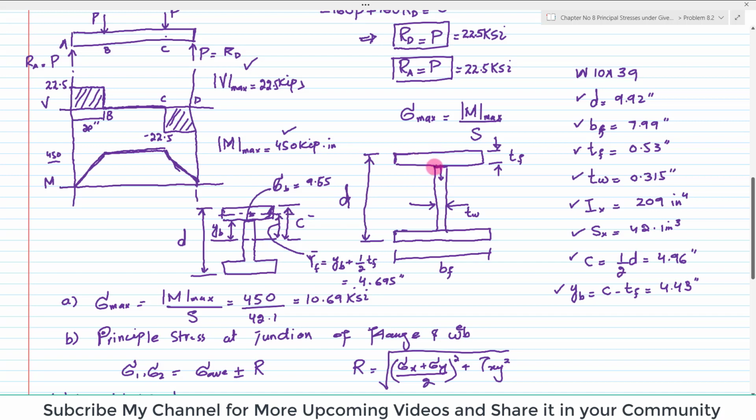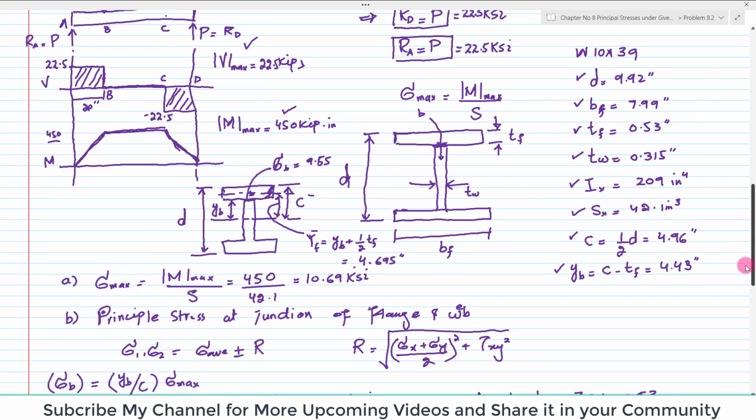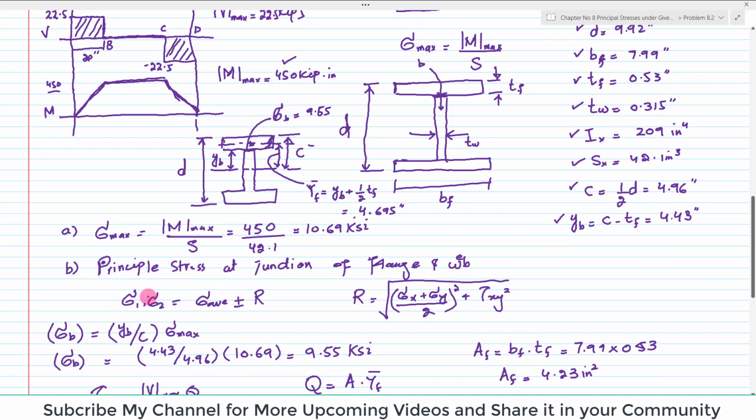Now in the second part, it is given to find out the stress at the junction of web and flange. So this is the junction, or this is the point B. So you can see this is the point B. You have to find the principal stresses at this junction. So for principal stresses, you know that we have the formula sigma 1, sigma 2 is equal to sigma average plus minus R, and this R is equal to this value.